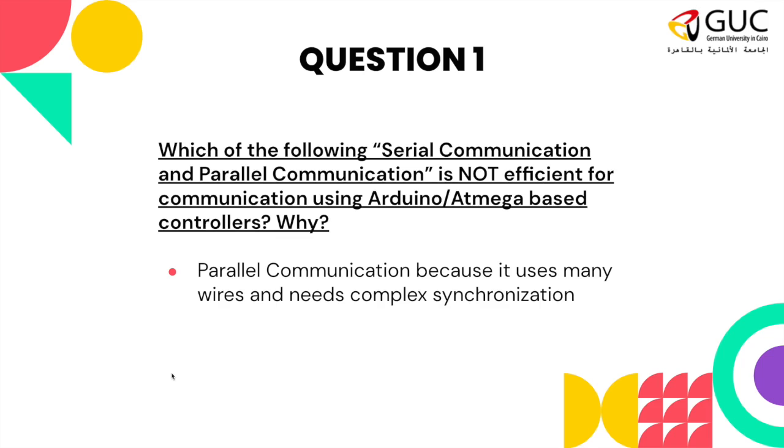It uses many pins. Plus, it needs complex synchronization, because imagine I'm sending 8 bits at a time. Now I need to make sure that all 8 bits will arrive at the same particular moment, and that a bit will not arrive faster than the other bits, or later than the other bits. So we need to maintain synchronization in parallel communication, which is hard because you're dealing with multiple bits at a time.